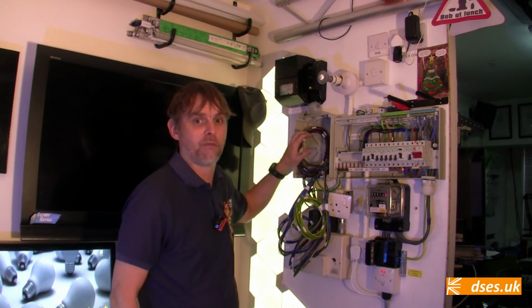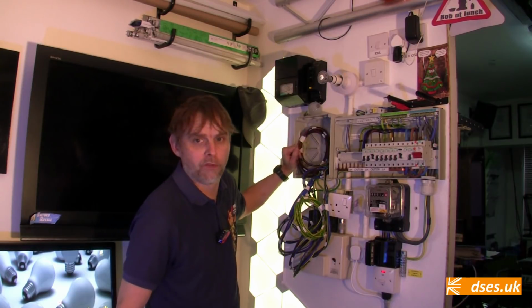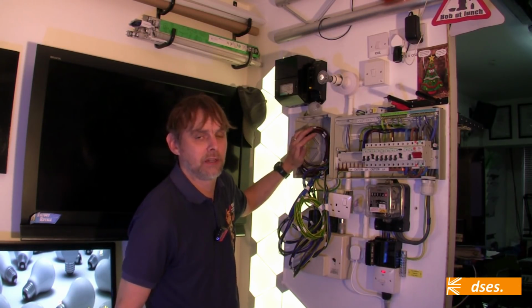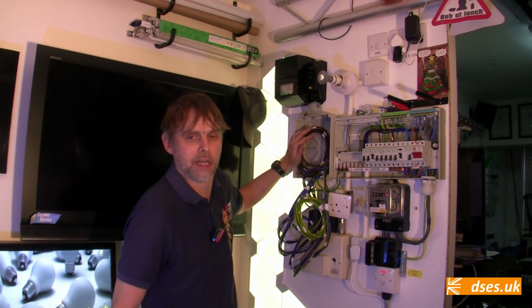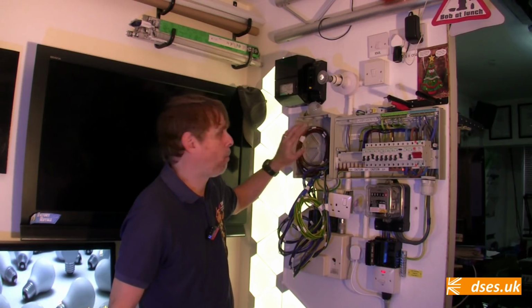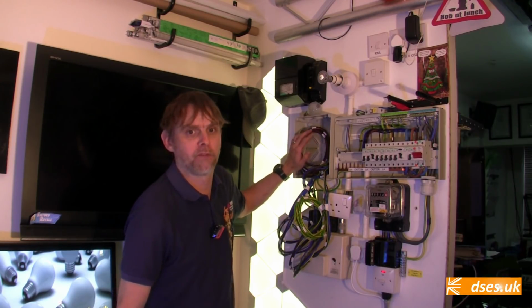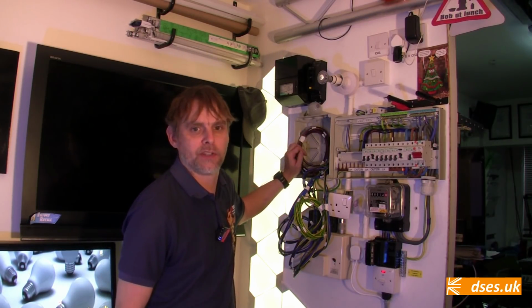We have the 2.5mm socket wire with its energised copper core, we have our 1.5mm lighting wire with its non-energised copper core, and we have an insulating dielectric between them, namely the PVC basic insulation and a bit of an air gap. Our wiring, when running this way, forms a capacitor. Between the 2.5 and 1.5mm conductors over the several metre distance of this cable, a tiny current is passing.